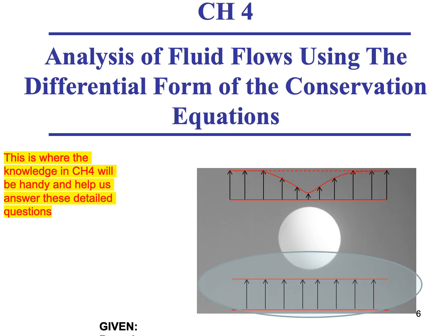So if we want to answer the question, what is happening to the flow right here, what is the velocity in meters per second of the air that's coming out of the hairdryer at this point, we really need to do a differential analysis of this flow using the differential form of the mass and momentum conservation equations.